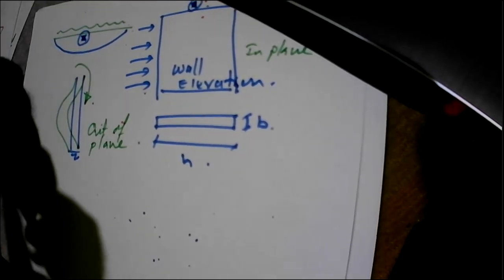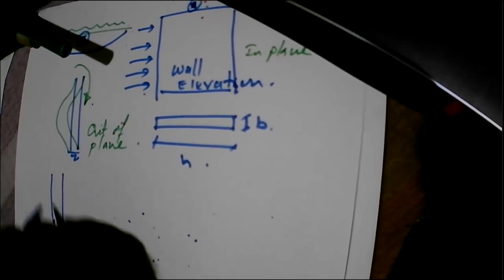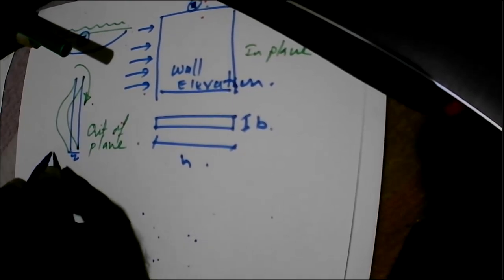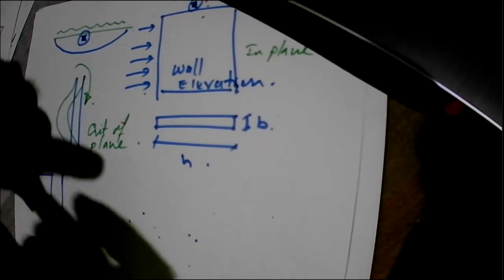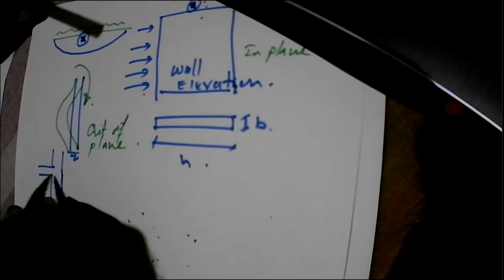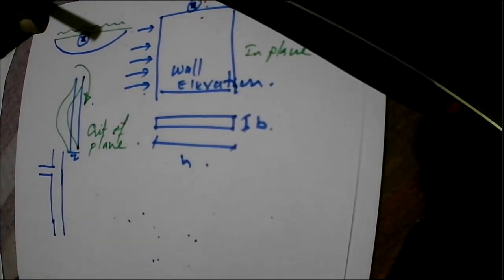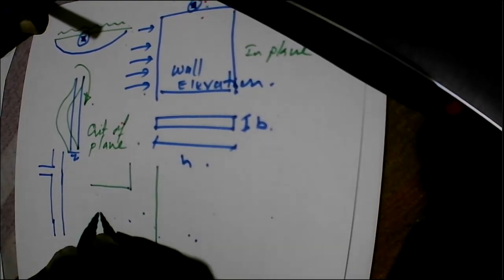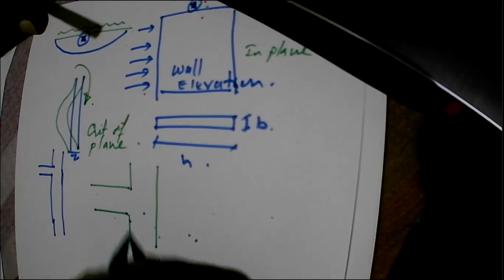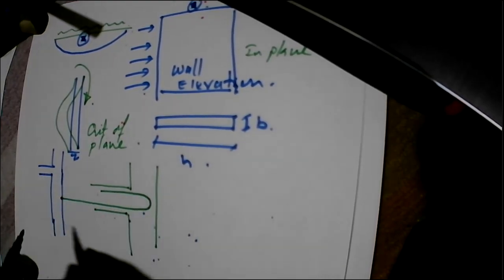And how we achieve this is, generally when you have a wall, and if you want to minimize the bending moments transferred onto the wall due to a concrete slab supported by the wall, what you do is at the beam column junction, you will provide some reinforcement at the top.